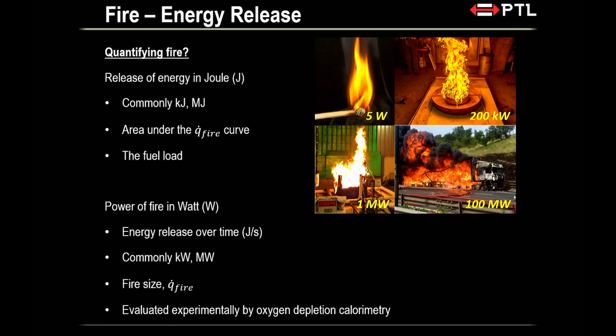Now, if you have a tanker and you stick it inside a tunnel and it becomes fully developed, you might be looking at 100 megawatt. Now, that is a big concern. Right? So these are the different fire sizes that we have. Now, how do we measure these heat release rate?